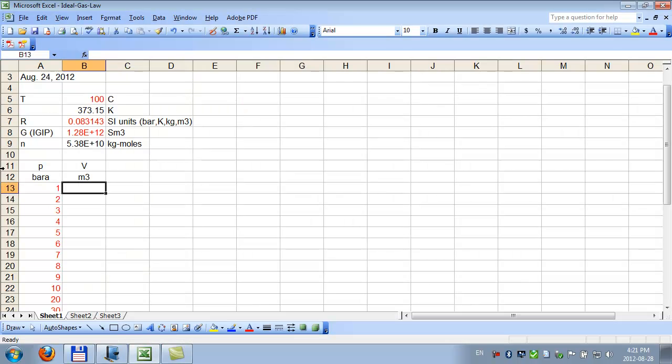So in this Excel sheet, we're going to put this equation in here. And that equation starts with an equal sign, as you know. And I'm going to group together these 3 numbers, which was the number of moles. And because it's a fixed address, when I copy that formula down to the next cell in row 14, I want it to be the same, B9. So I use F4, which is kind of the key to fix the address. You can cycle through with the F4 to make this a fixed address, either in column or row, or neither, or both, which is what we want here.